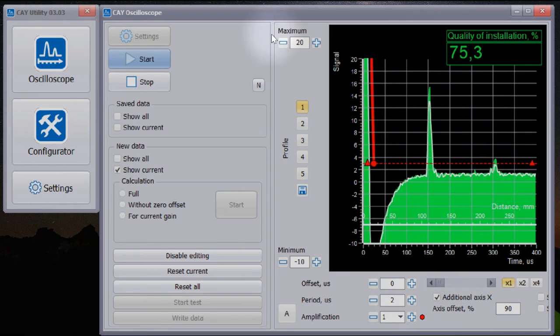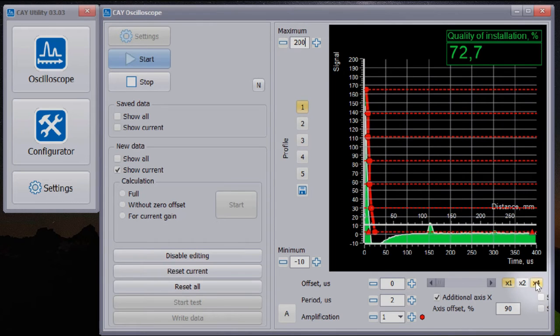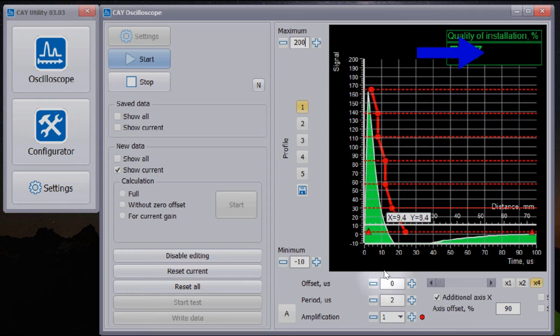Increase resolution of time. And for every scale coefficient, we added our filtering curve. Left mouse button allows to move filtering curve at single point for each scale coefficient. With right button, we can move all points of curve.